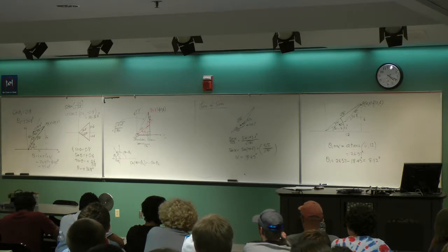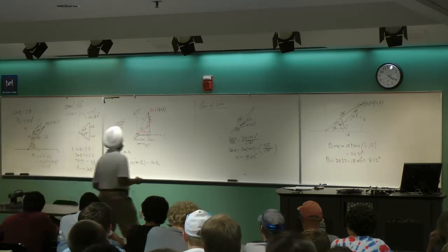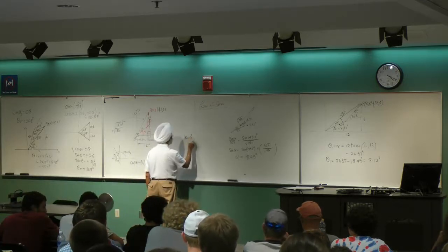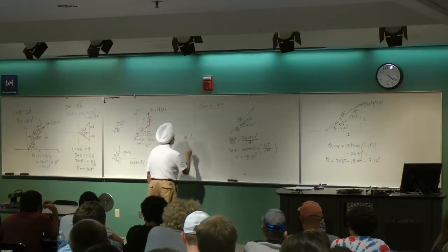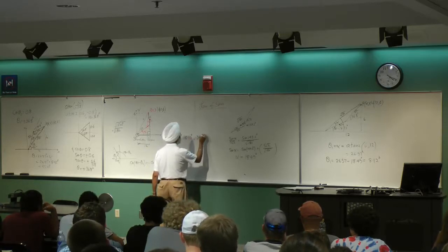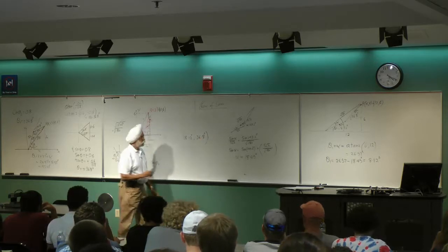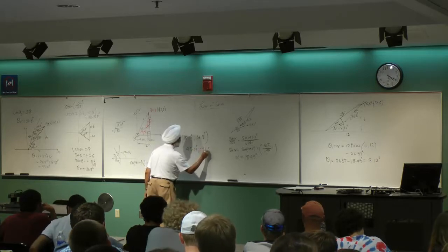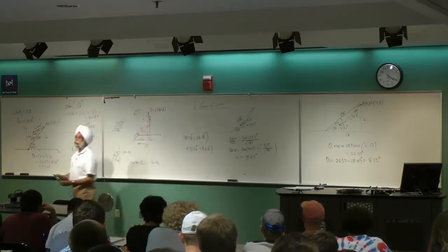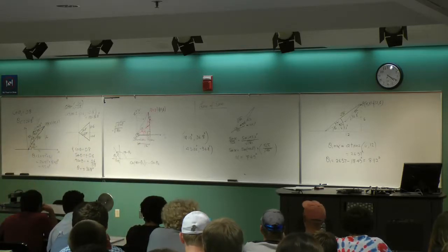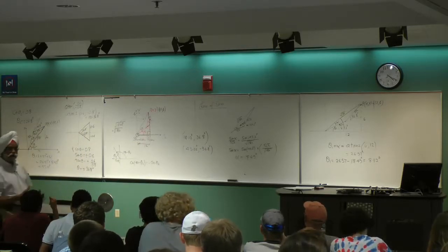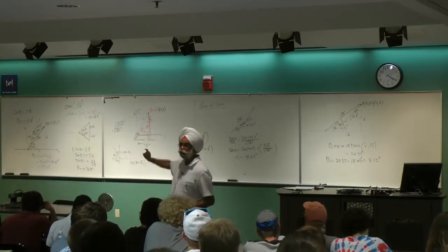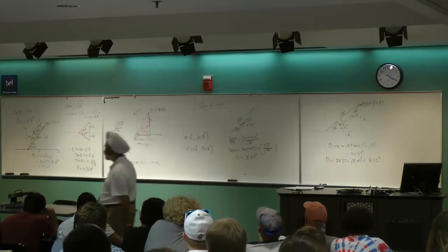So depending upon that, two solutions are what? One solution is 18.12 degrees theta 1 and the corresponding value of theta 2 is plus 36.8 degrees. That's one solution, right? The other solution is 45 degrees, 0.02 if you want to call it, minus 36.8 degrees. So we can reach the same point in space, not in space, in a plane, right? We have x, y only, right? By two ways, right? Those are the two solutions. And that's what basically we have.